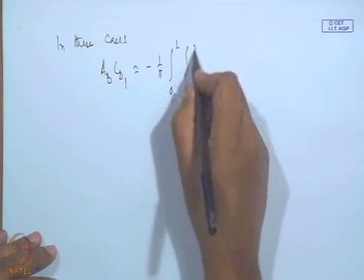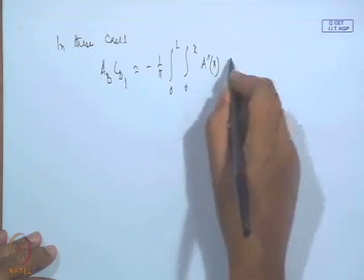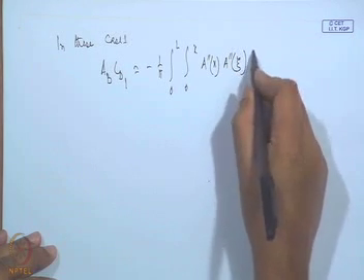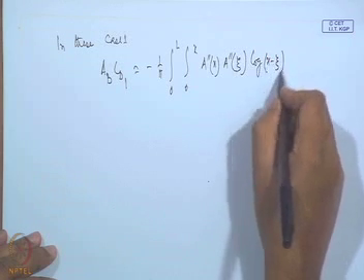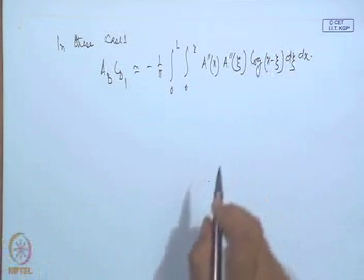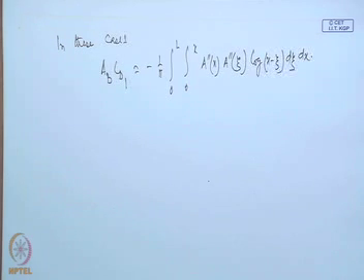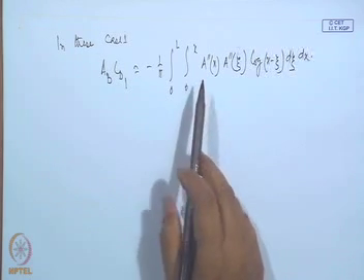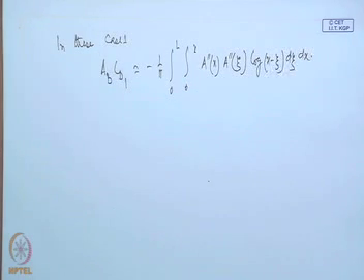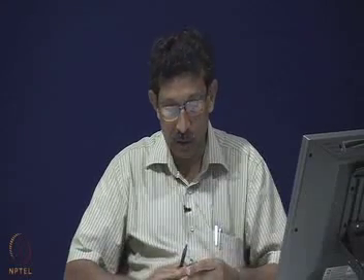Zero to L, 0 to x. Which happens to be that integration over a triangular area bounded by xi equal to 0, xi equal to x and x equal to L. So, we have obtained the drag coefficient due to the surface pressure distribution for a body of revolution of slender cross section with arbitrarily smooth profile and a pointed nose.